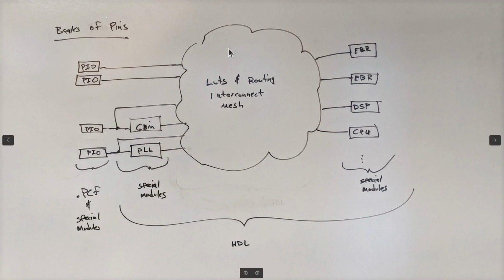We've seen the top level module. We've seen that we name the ports that come into and out of the top level module in our Verilog code, and we've connected that to the names of the pins in the PCF module. Next time, we'll spend more time focusing on what's going on inside this big cloud inside our modules, and less time worrying about how to connect them to the outside world.